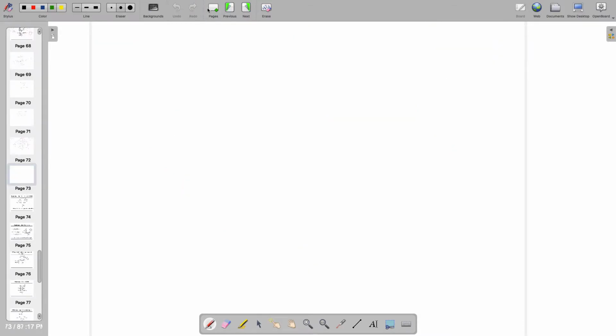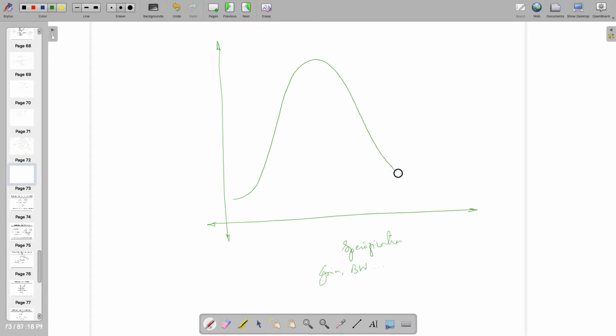When they are doing this, if you are targeting some specifications like gain, bandwidth, or phase margin, one of them will be taken, and for 10,000 runs it's going to be checked for Monte Carlo results. So here the number of occurrences will be there when you are running the Monte Carlo, also known as the statistical mismatch analysis.